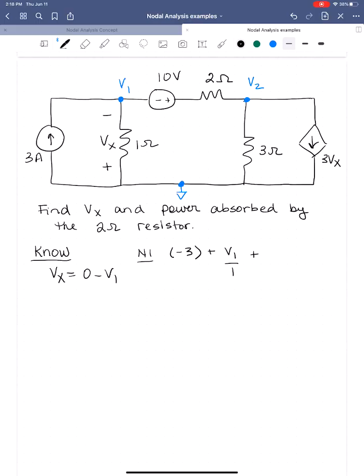Now this is a little different because now we have this voltage source here and ground isn't on one side. So this is going to take a little bit of work to figure out. I'll put a green node in here, a green node there. What we're trying to find out here, again, we're solving for the current flowing in this direction. So we need the voltage drop with that polarity across that resistor. At the minus terminal, we know what it is. It's V2. So we need to know what that node voltage is in order to figure out what that voltage drop is.